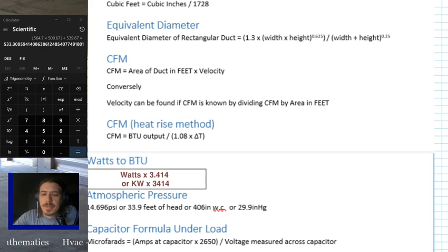Let's go back to our 20 by 10 duct, all right? We had our 20 by 10 duct we were talking about earlier. And we wanted to use round instead of rectangular, or for some other reason we needed to know the equivalent diameter of it. When we do duct sizing, this is going to come up a lot, so it's a good way to be able to predict this stuff. We have a width of 20 and a height of 10. We can put this in Excel pretty easy, and you might want to watch a couple videos or practice it. If you don't want to do it, that's fine too, but I figured I'd just show you guys in case you've never done it before.